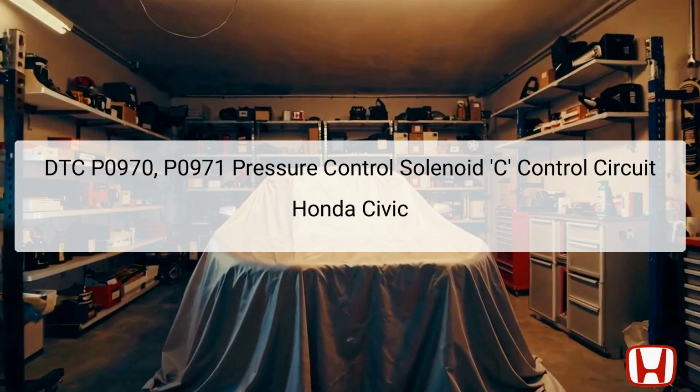These codes are specific to the continuously variable transmission CVT system, which utilizes pressure control solenoids to regulate hydraulic pressure and ensure optimal performance. The pressure control solenoid, specifically solenoid C, is located within the valve body assembly of the transmission. This component plays a vital role in managing clutch engagement and disengagement. Importantly, the presence of these DTCs suggests an electrical circuit malfunction rather than a mechanical failure within the transmission, which is crucial for accurate troubleshooting.